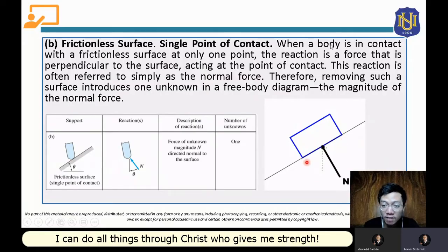It's the same here. If the reaction here is a rectangular load, we can compute its equivalent point force, which will be this normal force. Its point of application will be at the center of the contact between this body and the surface, which is at this point.